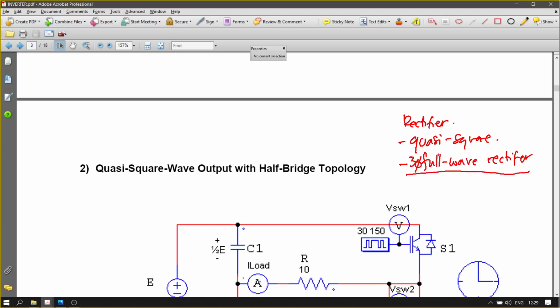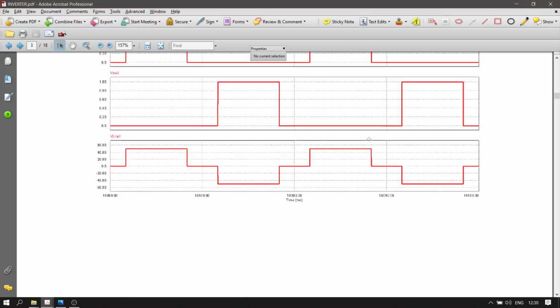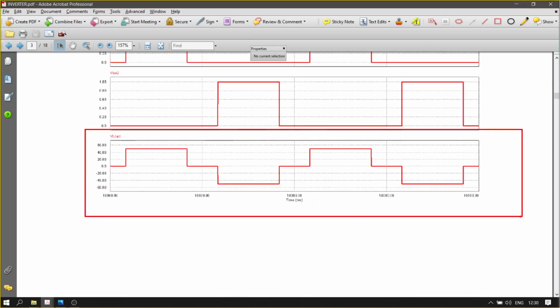So go back and look at this three-phase full wave rectifier, whereby if you have that, then this is your final equation, the waveform. So identify that there is 30 degrees here, and this is 90 degrees, and then you have 150 degrees, and that will be 180 degrees.